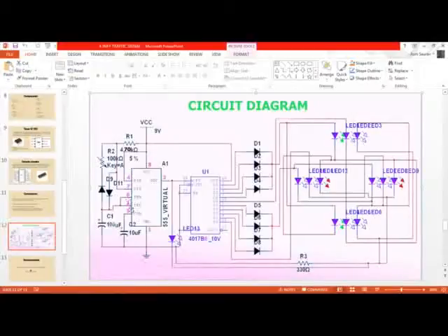On the next part, we also connected a 100 microfarad capacitor to the trigger and threshold pin, as you can see. And the ground portion is here. We made it ground, and we have also used a capacitor.